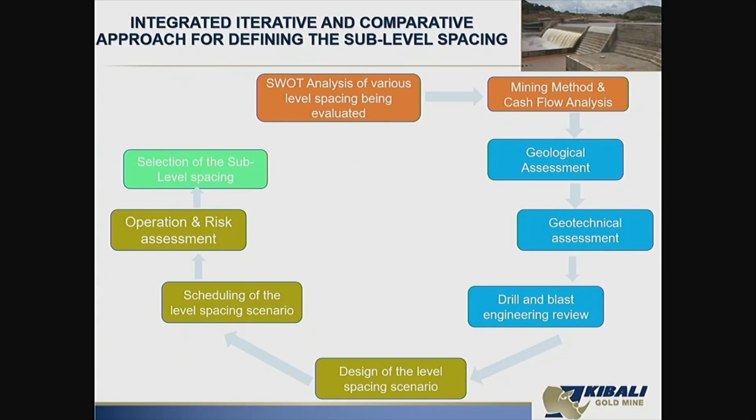The geology is king. So you always have to have a better understanding of the geology. You have to assess the geology first, from a confidence level perspective and from an understanding of the geology as well. The geotech is very important in an underground environment, especially when you're dealing with voids. Increasing the sublevel spacing means that you're making a bigger void. So you have to look at that. You have to do a detailed assessment on that.